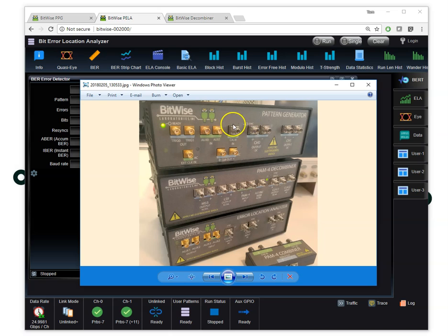I'm generating signals. I happen to be using our PAM4 combiner and creating a PAM4 signal using our live PAM4 decombiner to strip them apart into two NRZ streams. And then those two NRZ streams are what I'm putting into this analyzer. So we'll get a chance to put patterns in and study them, as well as play with thresholds and cause bit errors and study them in the result.